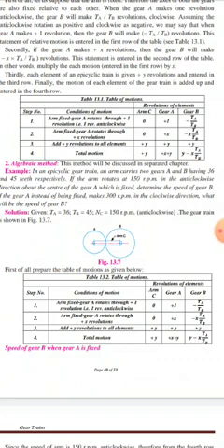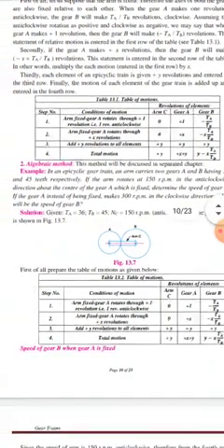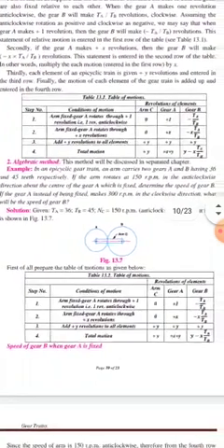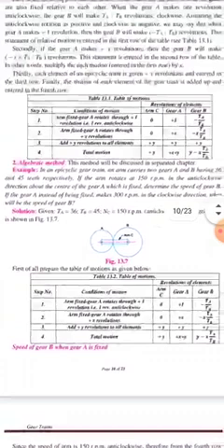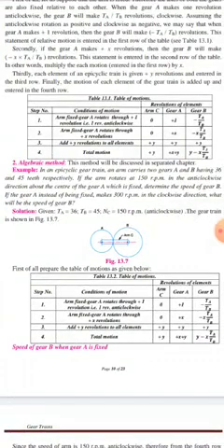In an epicyclic gear train, an arm carries two gears A and B having 36 and 45 teeth respectively. If the arm rotates at 150 rpm in the anti-clockwise direction about the center of gear A, which is fixed, determine the speed of gear B if gear A, instead of being fixed, makes 300 rpm in the clockwise direction. What will be the speed of gear B?